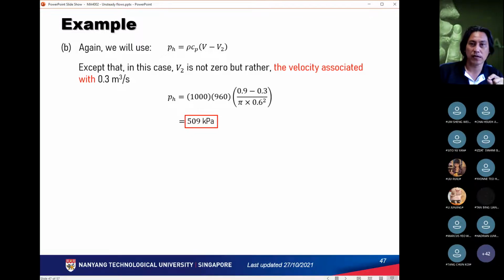When it comes down to the water hammer effect, this is something that I think I have to reinforce. That's the reason why, even though we do have powerful valves that can shut off the pipeline flow very fast, we try not to do that, because in a worst case scenario, gaskets and bolts and nuts may get blown out. Worst case scenario, the pipes may rupture, and I believe this is not something that you want to see.